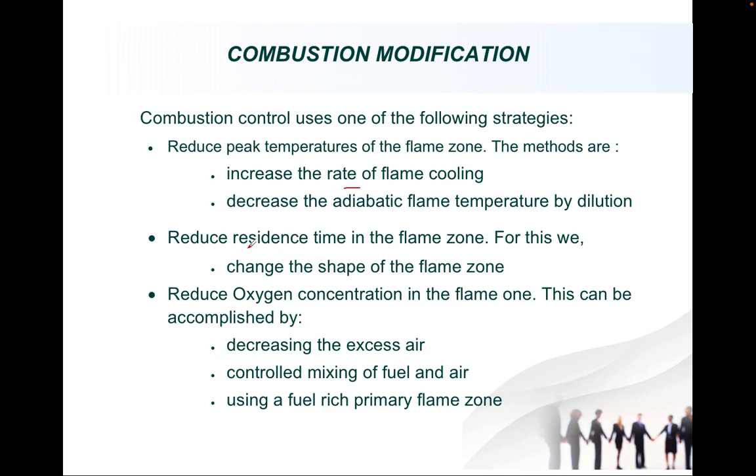This can be accomplished by decreasing the excess air, controlling the mixing of fuel and air, and using a fuel-rich primary flame zone. Now, why the oxygen? When oxygen is present abundantly or excessively in the combustion air or the combustion mixture, it will react with the nitrogen.